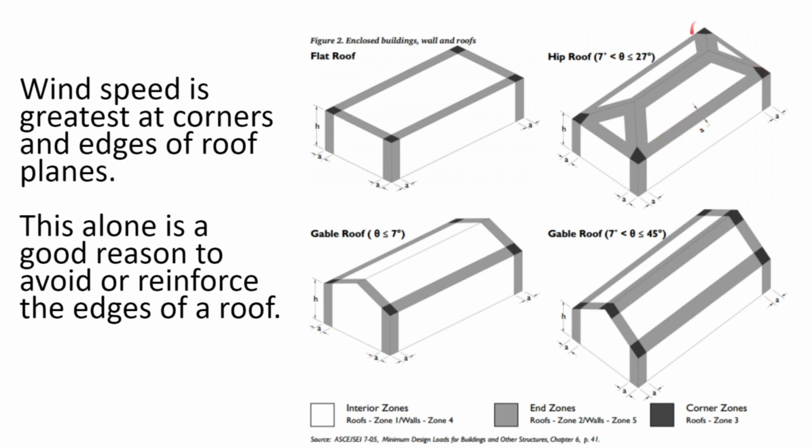The roof itself may overhang the structural wall, and so the attachments on the interior of the roof will be stronger if kept to the inside of the structural wall. The roof cap or ridge may need additional space for servicing. A design change in the field may be easier to implement if there's some empty space remaining on the roof.